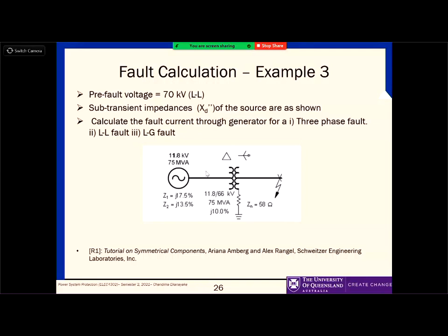Let's say you have 3 lines, and the same current is coming through those 3 lines. What happens at the end? Then there's no way to take it away, because the addition of those 3 lines is equal to 3 times that current, and there's no return path to carry it away, so you can't apply the Kirchhoff current law there. It violates the KCL, right?